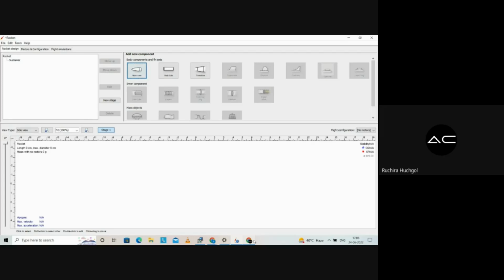The nose cone, you all must know, is the very first part of the rocket body that comes into contact with the airflow. So what it is doing is trying to provide less contact area, so that there is less friction between the rocket body and the air that is flowing, right? That is, it is trying to minimize the friction, and in turn minimize the drag. You all must be aware of the aerodynamic forces that act on a rocket, which are lift, drag, weight, and thrust. So in order to overcome drag, we minimize the area of the nose. That is one of the purposes.